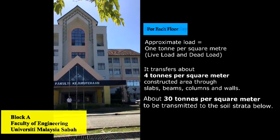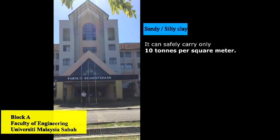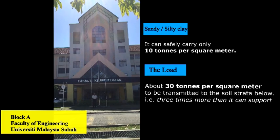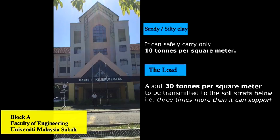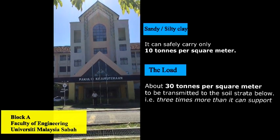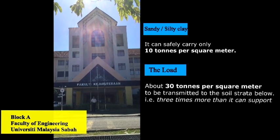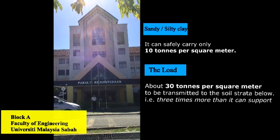This amounts to about 30 tons per square meter to be transmitted through the supporting walls to the soil strata below. The soil here is sandy, silty clay and can safely carry only about 10 tons per square meter, while the load from the superstructure is about 30 tons per square meter, that is 3 times more than it can support. Hence, we have to introduce a structural interface between the superstructure and the soil, such that the load coming from the superstructure, about 30 tons per square meter, is spread over sufficient bearing area to make it safe for the soil to carry it, about 10 tons per square meter.